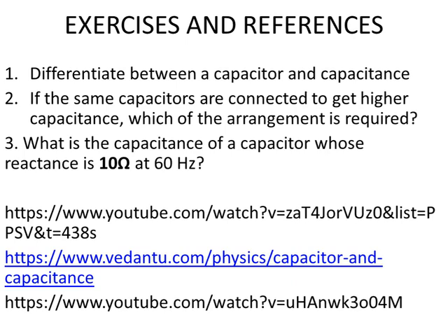Now, the formula for equivalent capacitance for a series combination is different from how it is gotten for a series combination of resistors. For a series combination of capacitors, in getting our equivalent or total capacitance, 1 over C equivalent equals 1 over C1 plus 1 over C2 plus 1 over C3, depending on the number of capacitors we have. And C1, C2, C3, C4, those are the capacitances that we have in the circuit.